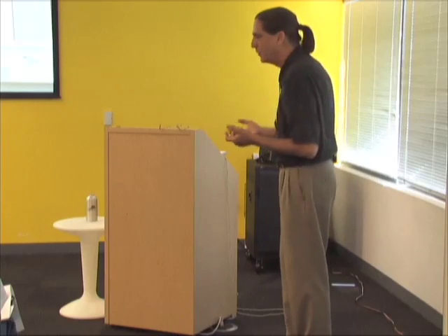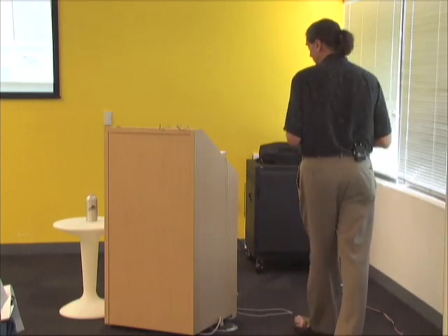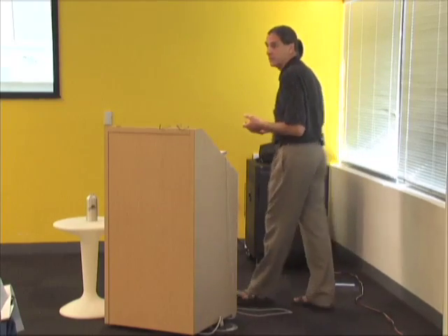And number 4, you need to use components. I did a little test the other day just to prove it to myself. I made 8 boxes, and then I made one box, called it box, and made 8 of them and checked the file size. It wasn't 1/8 of the size, but it was much smaller, maybe 1/6 the size. So components will radically drop down the size of your model.